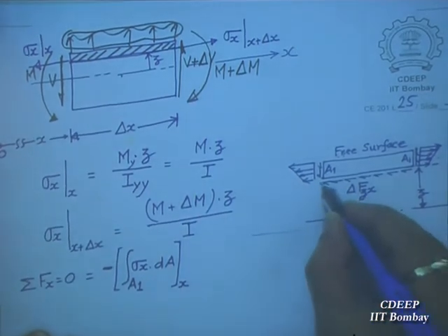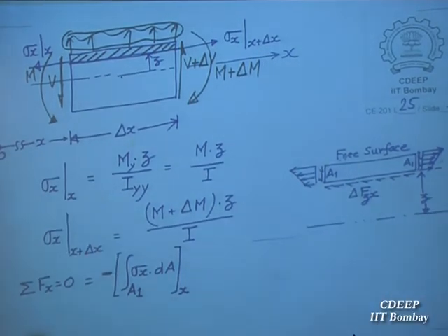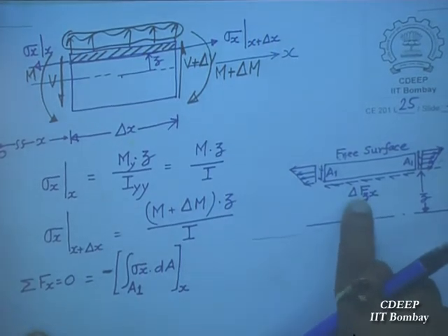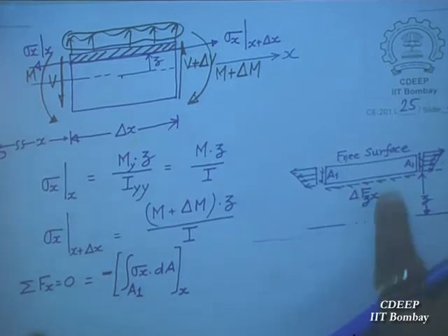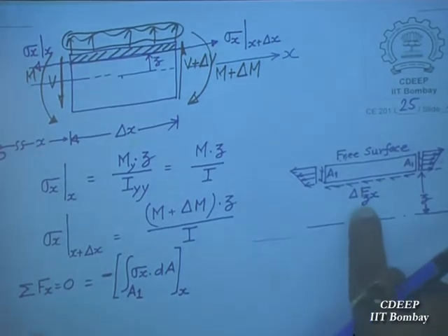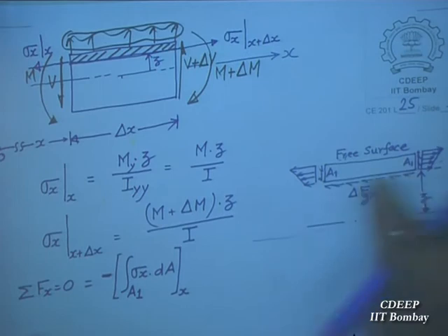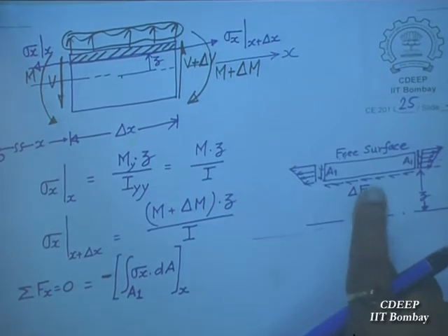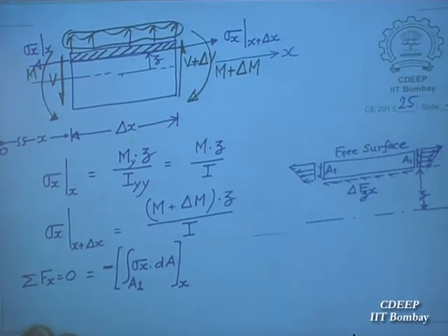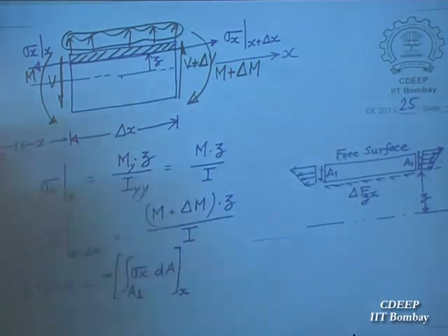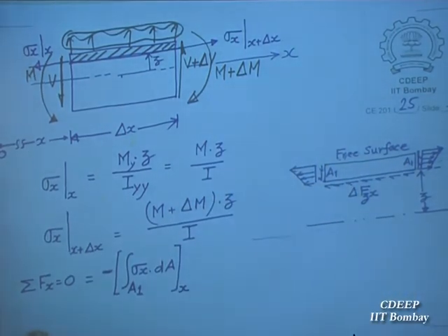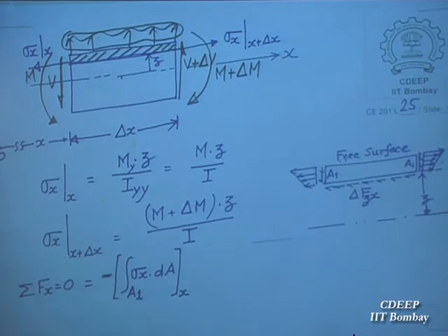Then this force. See, bottom force. I have given not stress. This is Fzx. What is F? F means force. What is Z? Z is the normal. Normal to this surface is Z direction. Negative Z direction, Z downwards. So it is Z. And what is the direction? X direction. This is in negative X direction. So I have just given Fzx. So this is the total force on this surface. Total force comes because of stress multiplied by the bottom area. Bottom area will be this length dx multiplied by the width of the beam. You understand that? Bottom. Okay, so that is the total.